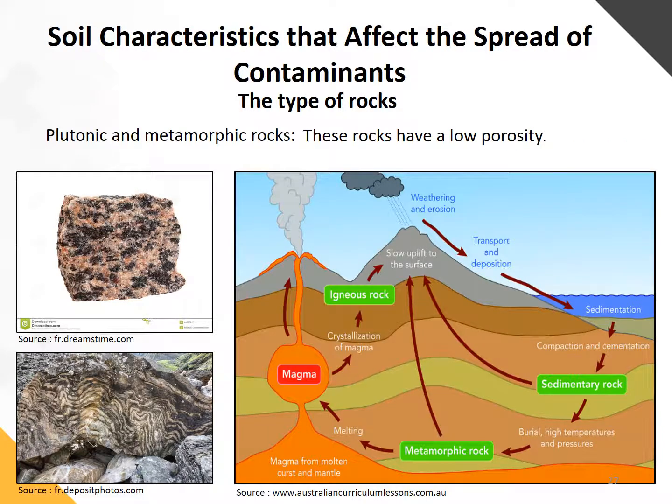Plutonic and metamorphic rocks are very hard rocks with very low porosity. These are rocks that mostly have fracture porosity. There is practically no empty space between the crystals, and in the absence of fracturing or alteration, the porosity is zero. Unless severely fractured, these are environments where the possibilities of contamination are very low. Plutonic rocks are mainly present in northern Quebec, and metamorphic rocks cover a large area along the St. Lawrence River, found in both Abitibi and the North Shore.